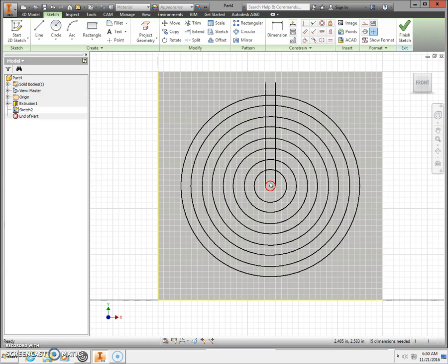Now before I trim this out, I also want to have this one from the top going out to the right hand side. So I'm going to do a line tool again. Make sure I'm at the 12 o'clock position on that innermost circle. And bring this out. Make sure you have your straightness snap or that object snap located. And I'm going to go from the bottom again.